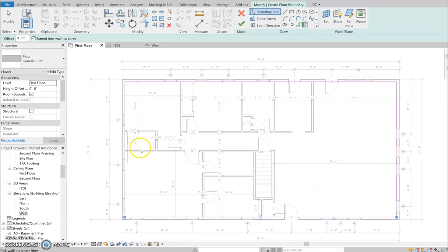We know that our beams are under this wall horizontally and this wall right here. So technically, we could adjust this and get our floor joist system in the way that we want. You're going to see these double lines right here. Your lines might be going horizontally and not vertically, and I'll show you how to change that in a second.